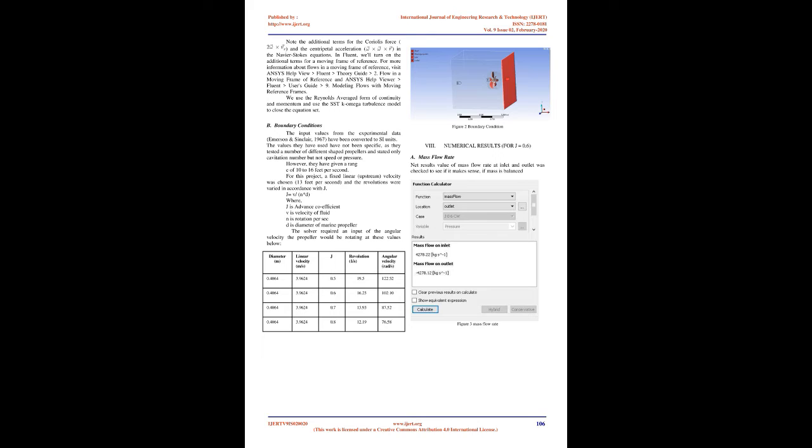This model was further used to develop a CFD model to get the effect of rotation of the marine propeller at different advance coefficient values, J. The CFD data and different settings were used with reference to previous literature work done on wind turbines. The results obtained from CFD analysis were transferred to static structural analysis as a part of one-way FSI simulation. The pressure over the blade surface was mapped to the surface of the marine propeller blade for the loading boundary condition